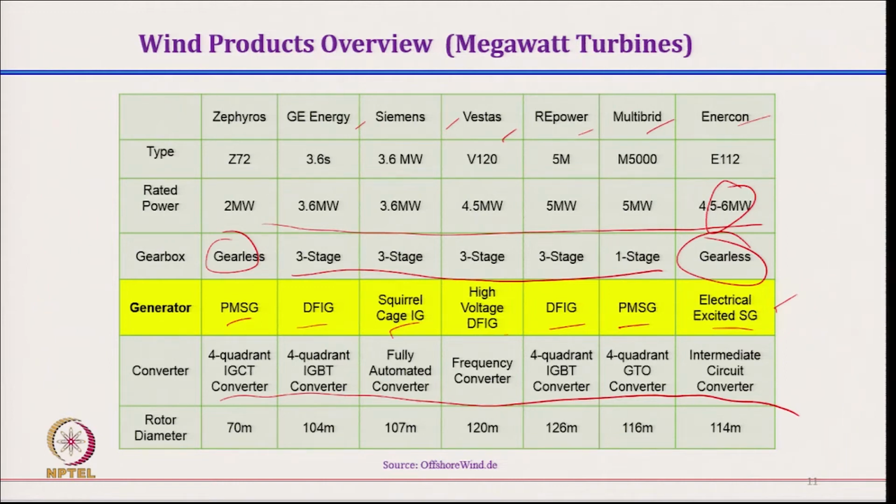The reason for power electronics converters is that you will be able to have the generation with maximum power tracking at variable speed, and you are able to generate around 50% more energy using the variable speed wind generation system. That is the reason a lot of power converters are there, either in the case of DFIG or other machines.